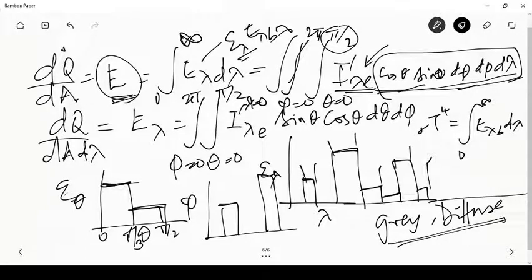So the gray diffuse assumption is something that we commonly use. So what we need to understand is that the gray diffuse assumption is a very, very gross assumption, and there are no gray diffuse surfaces that exist in reality. Okay, we always go with this premise that because the calculations are simpler, we learn to do this using the gray diffuse assumption. But when we need to calculate the real things, we will need to go into that complexity and learn to calculate the integrations as we have defined here.